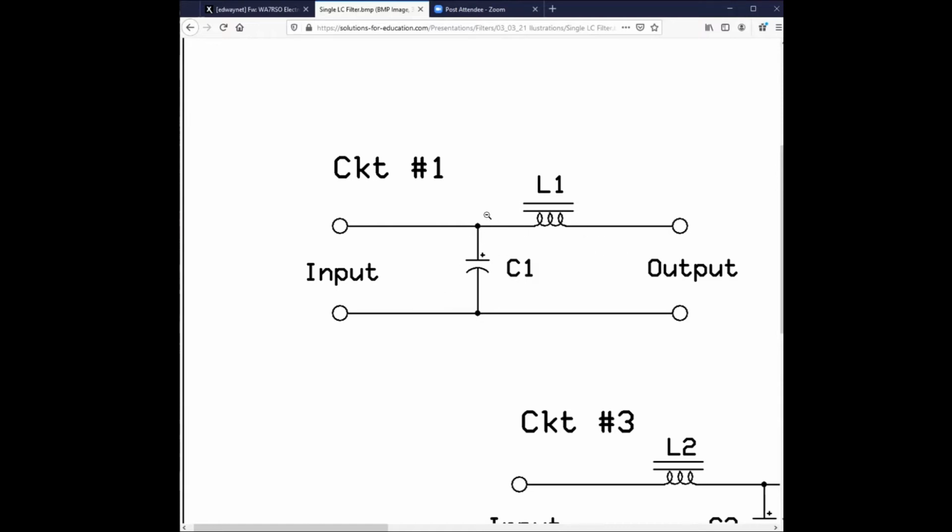Now, as frequency goes higher and higher, which is the rate of change, and that is another one of your very key words. If you don't have that word in there, rate of change, you're missing part of the picture. So what you're saying is that rate of change is really, guess what? Frequency. Hence, we have our formulas, which are 2 pi FL for the inductive reactance, how this reacts to a change in current. You've got to get across to this individual, where this is a new thing for them. If you helped anyone else, you've probably noticed that there are certain areas of electronics they have a lot of trouble absorbing. I think this is a major one right here: inductance, reactance of that inductor, reactance of this capacitor.